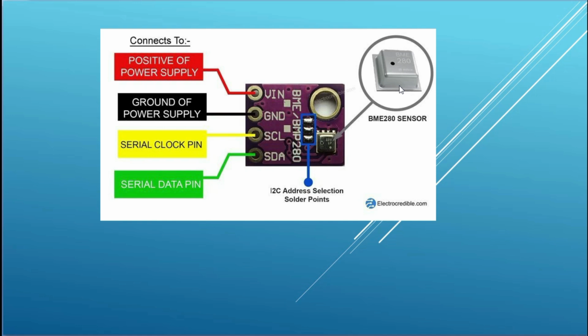So when we read the pressure, we also have to read the temperature so that we can compensate the pressure for a given temperature. As you can see, the board is easy to hook up. You just connect your plus supply to the processor voltage output, and one line goes to ground, and then all the communication to the board is done over I2C serial.